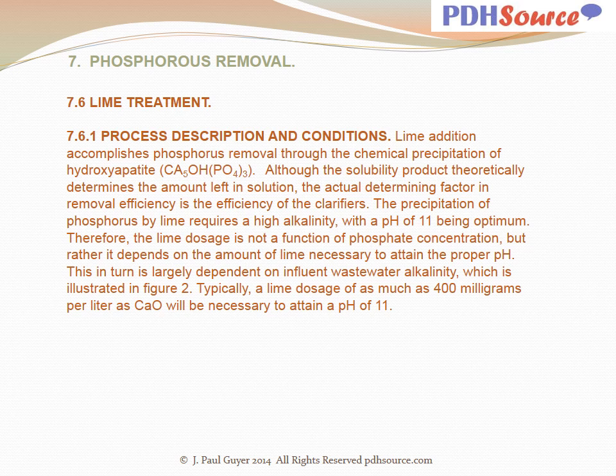With regard to lime treatment as an approach to phosphorus removal, lime addition accomplishes phosphorus removal through the chemical precipitation of hydroxyapatite. Although the solubility product theoretically determines the amount left in solution, the actual determining factor in removal efficiency is the efficiency of the clarifiers.